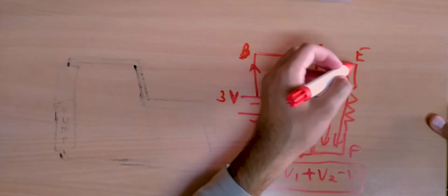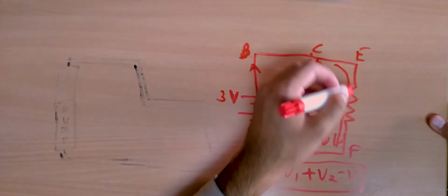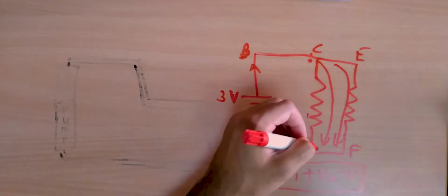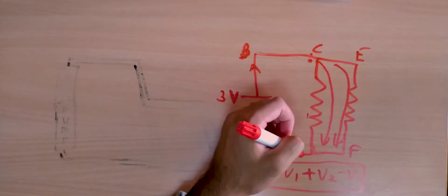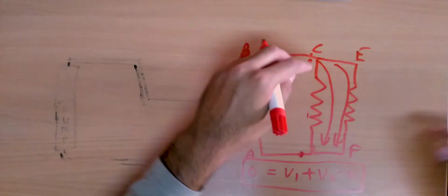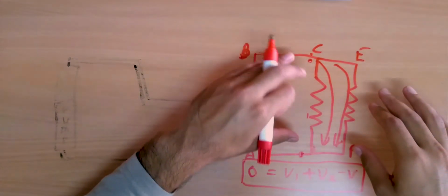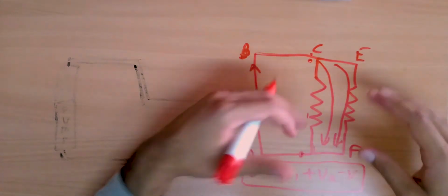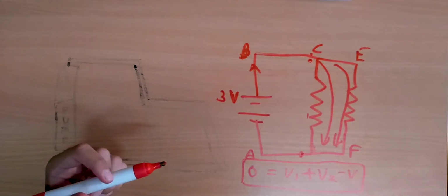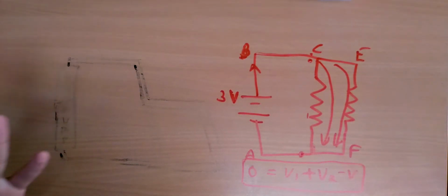And even if it moves through that section of the circuit, it has to lose those 3 joules of energy. And that's the simple reason why the potential difference across two resistors connected in a parallel arrangement has to be equal.